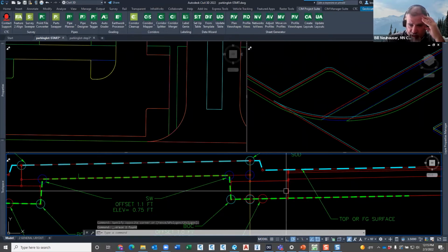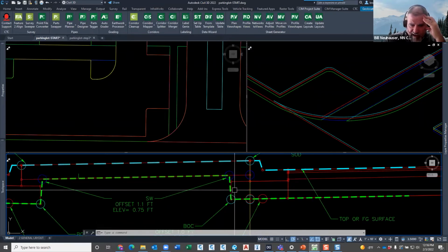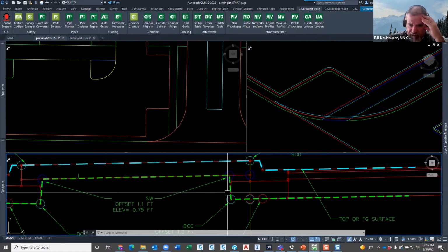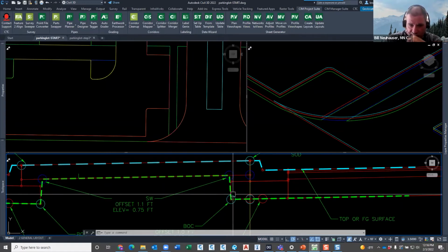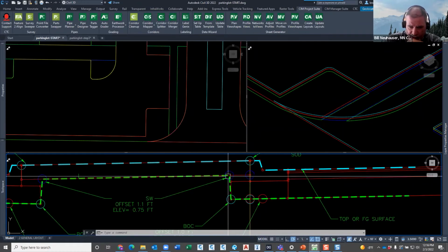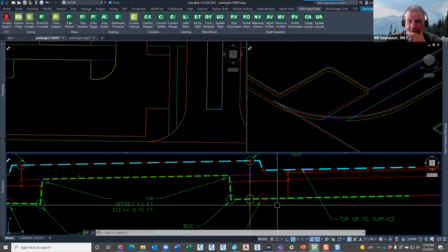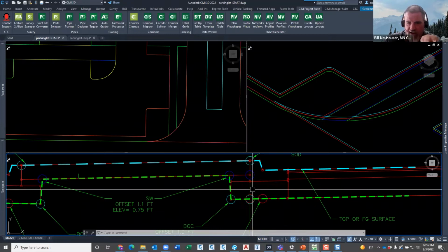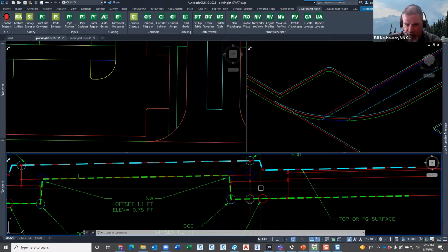The software is not smart enough to figure that out. So what we do is we set just a slight offset in any of our vertical lines on our surfaces. We want a slight offset, and then the computer goes through here and connects the dots in the proper order to determine our datum surface. Now, since we're going to offset these a little bit, why not offset them in the correct spot?